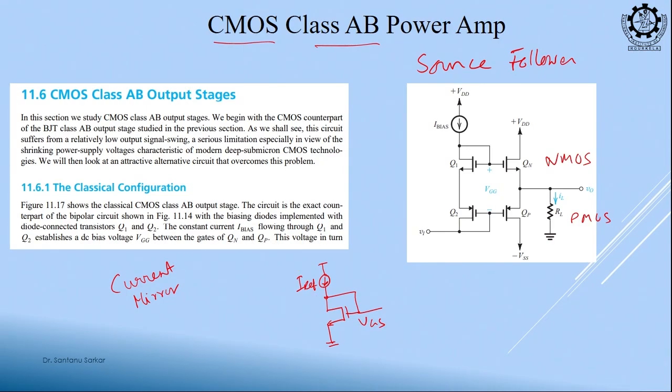Okay. Now, this is my main circuit. If we add this node voltage to the gate of another MOS, its VGS and this VGS are the same. So ideally this should also carry the same current, but due to channel length modulation this may vary a little, because the drain voltages are different, they are not tied. The gate voltages are tied, but the drains are not tied, right.